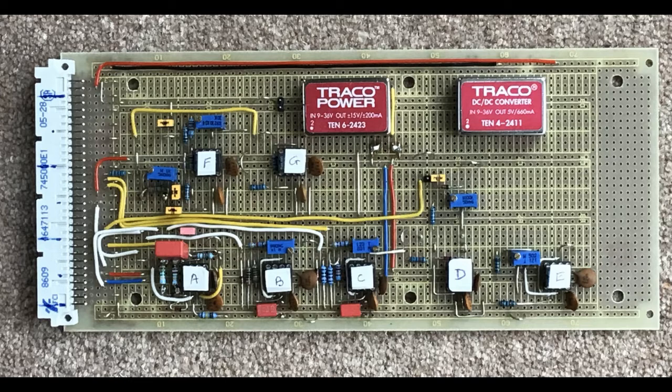At the top of the board are 2 DC to DC converters, powered by the lead-acid battery or batteries. The first converter provides stabilized plus and minus 15 volt supplies for the op-amps and their associated circuitry. The second converter provides a stabilized plus 5 volt supply for an incremental encoder used in the speed and distance measurements and some other devices. These Traco converters turn up on eBay from time to time and are an excellent buy since they will operate efficiently with an input voltage that varies from 9 volts up to 36 volts, and they have a very good specification.